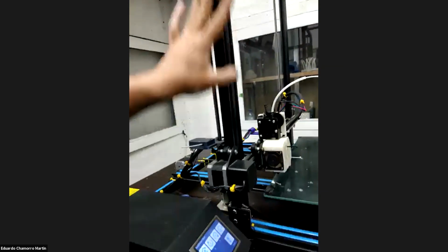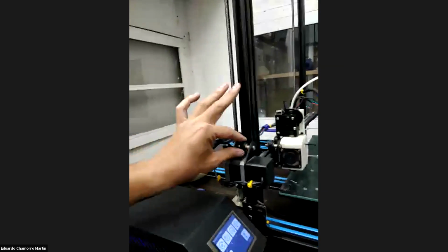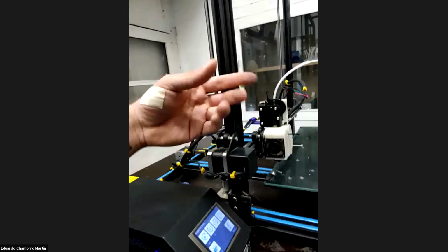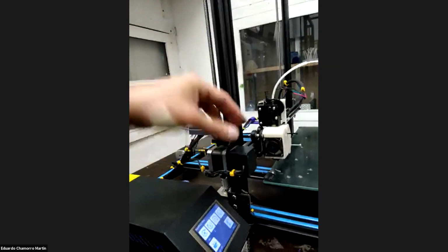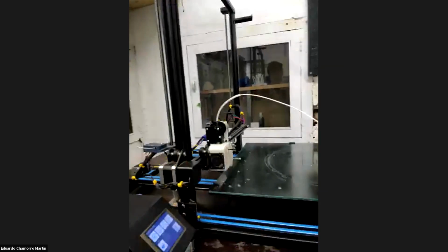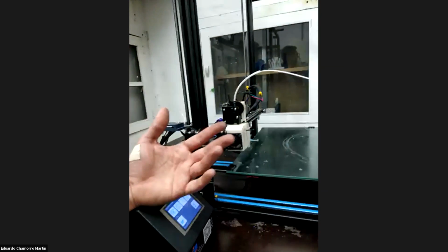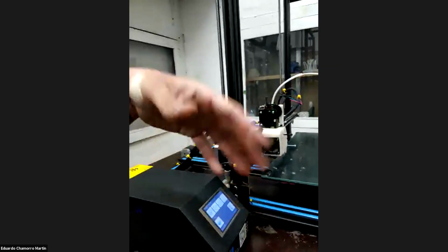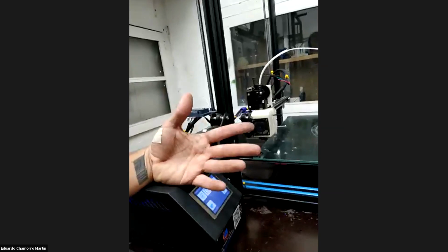What is the limit of the accuracy of this machine? First, how straight are these profiles? Usually they are not micron accuracy. They are like 0.5 millimeter accuracy. Second, the wheel is a plastic part, usually not machined like metal, so it has reduced accuracy. That's why this machine became so cheap, because it greatly reduces the manufacturing costs and the cost of accuracy. So they are good platforms, but you can upgrade them a lot to make them print really, really well.